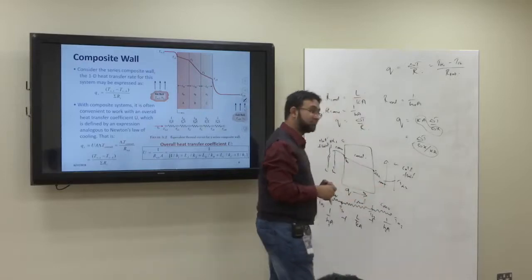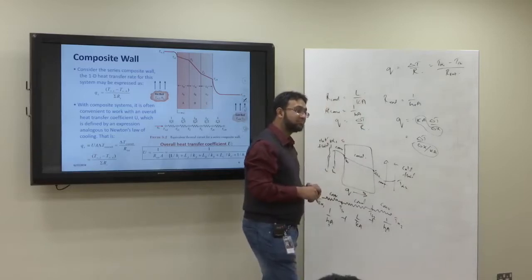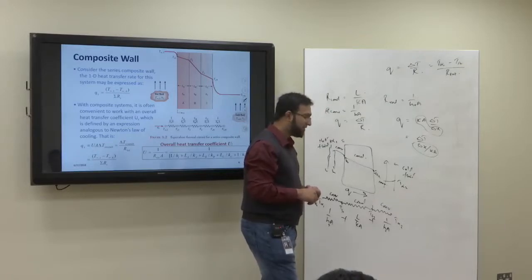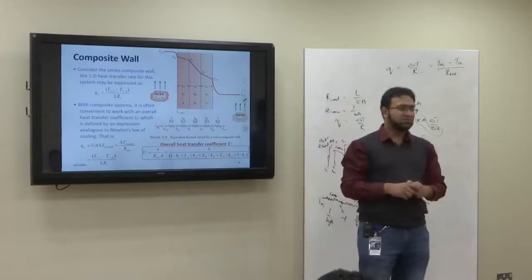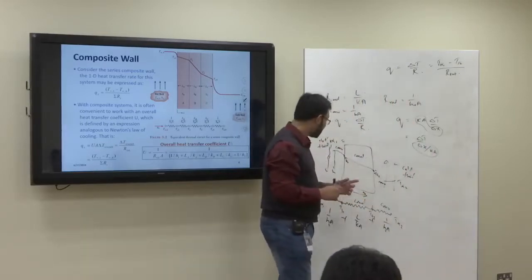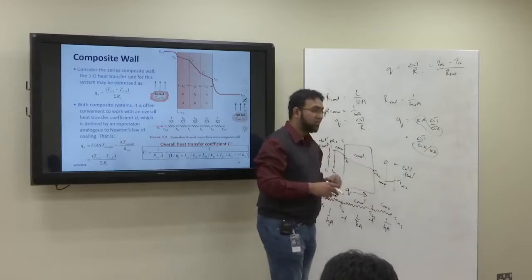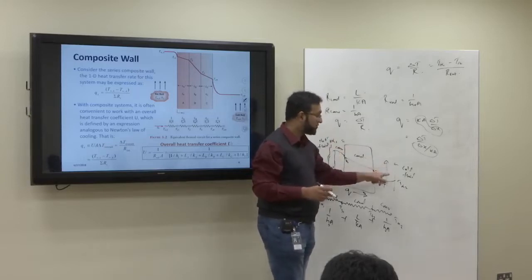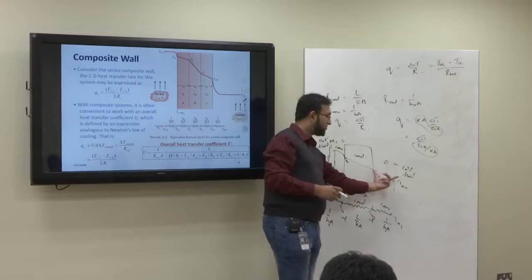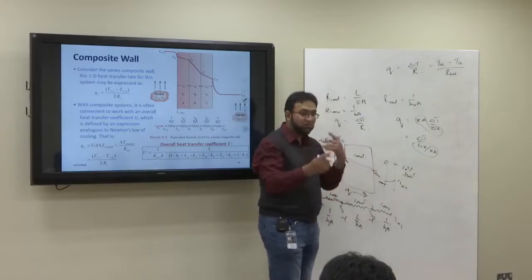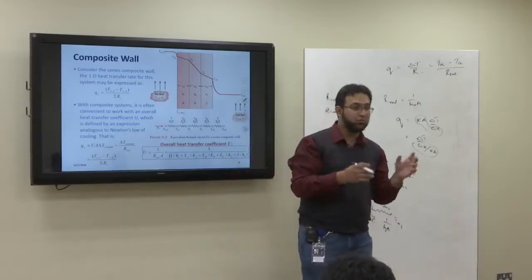In each question, if I do it like this, I should consider the start point and the end point, then communicate with the other points in the series. So look, it depends. Suppose you are not concerned about the temperatures Ts1 and Ts2, you don't need them. Then solve it from start to the end. Suppose you have the cold water fluid temperature, but you do not have Ts1, then you can consider only this region. So the cold fluid temperature you already have, you can find Ts1. It depends on what you need and what procedure you have to follow to find it.